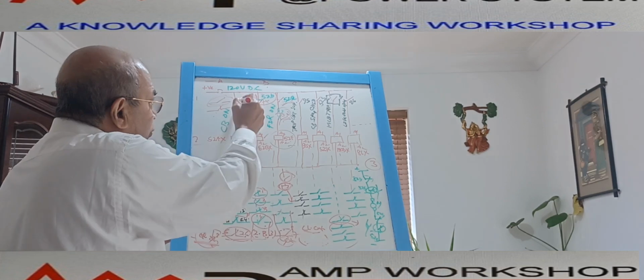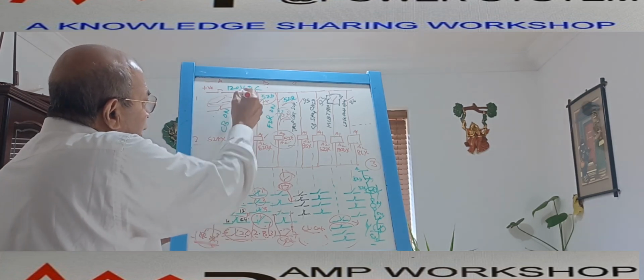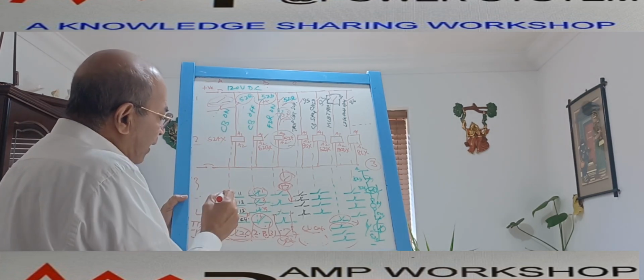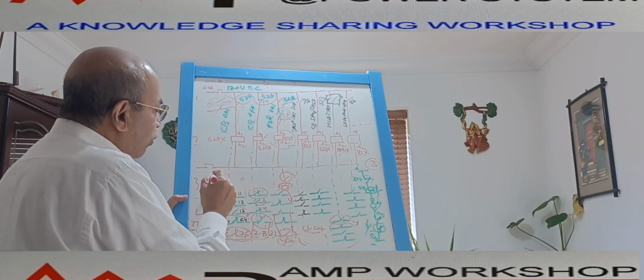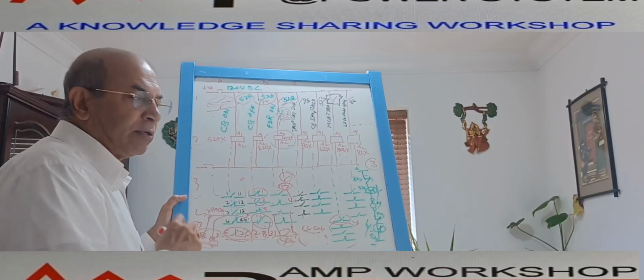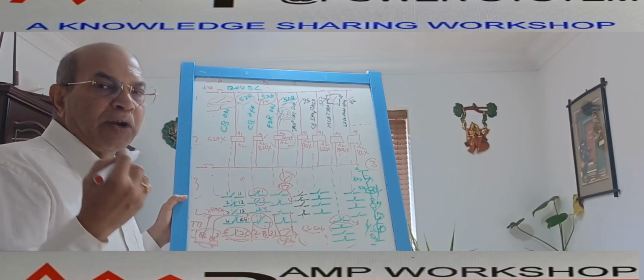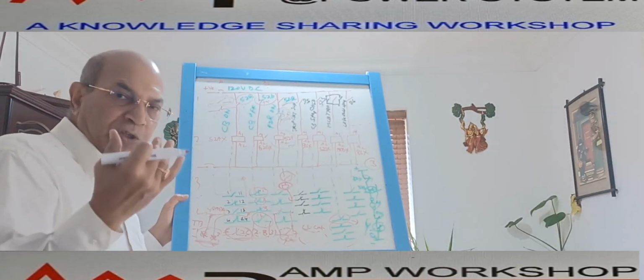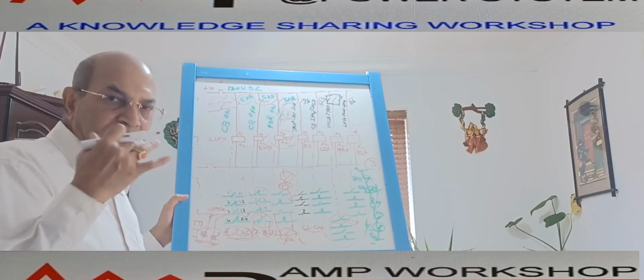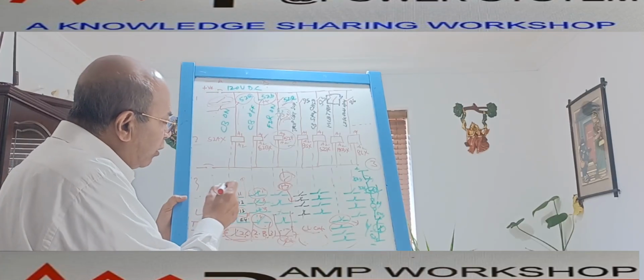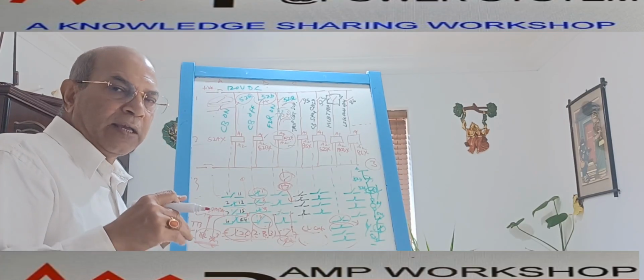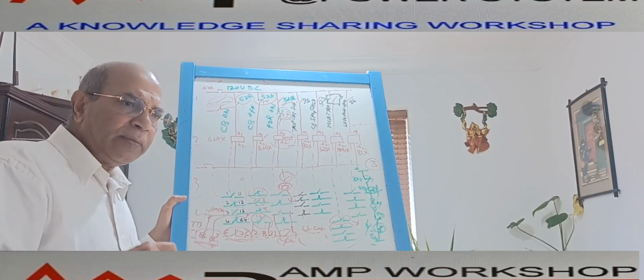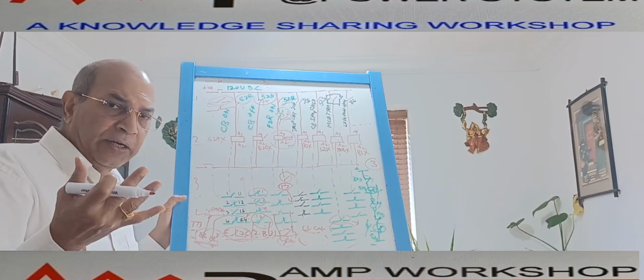Suppose this is circuit breaker on. So this is only 52A. But in this condition, if I take this signal to the control room to understand the power is flowing, sometimes it may be true, sometimes it may not be true. If the disconnector is not on and the breaker is in test position, not in service position, in that case it will give a wrong indication. That's why circuit breaker on and feeder on are two different indications.